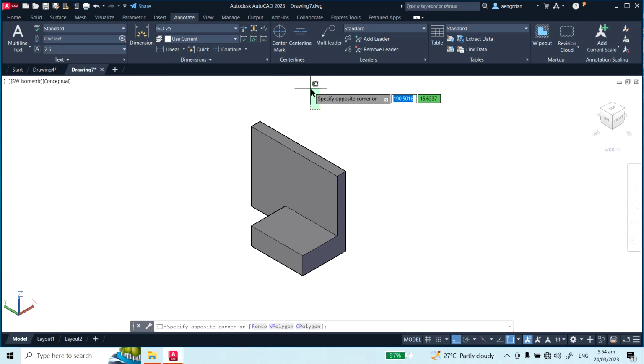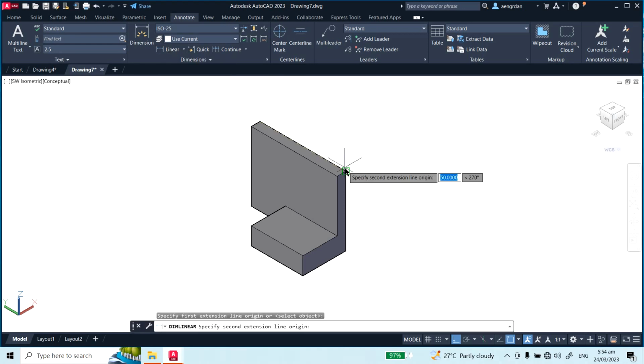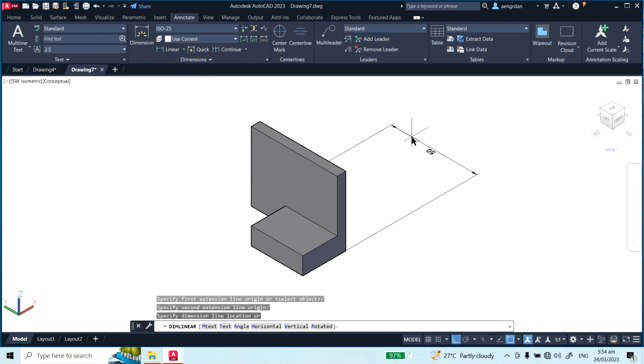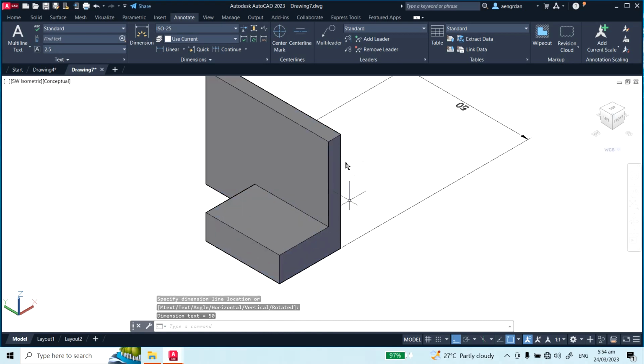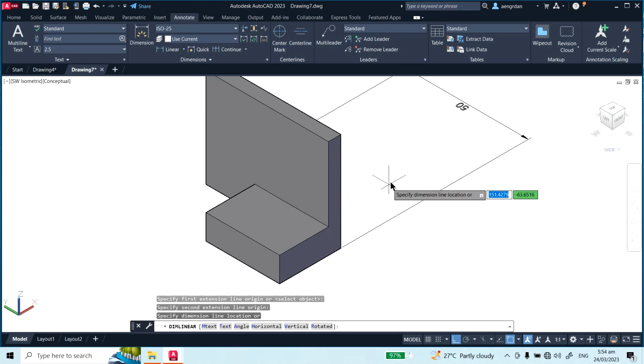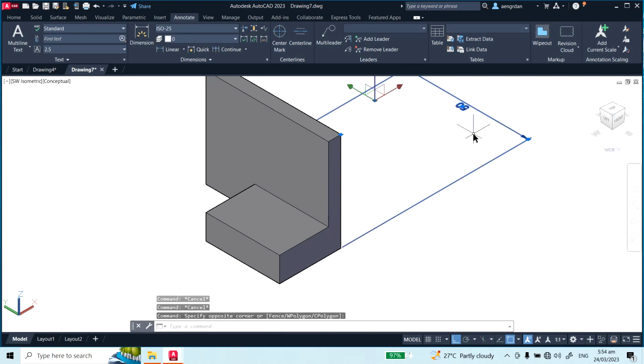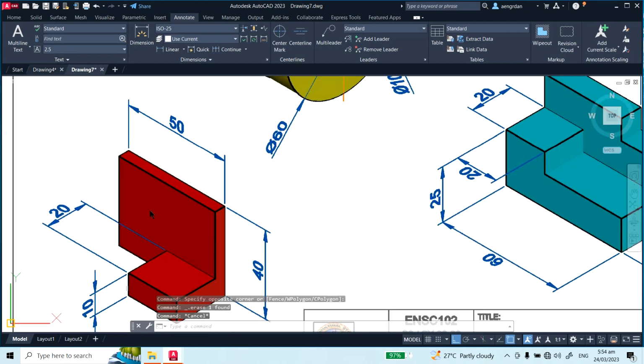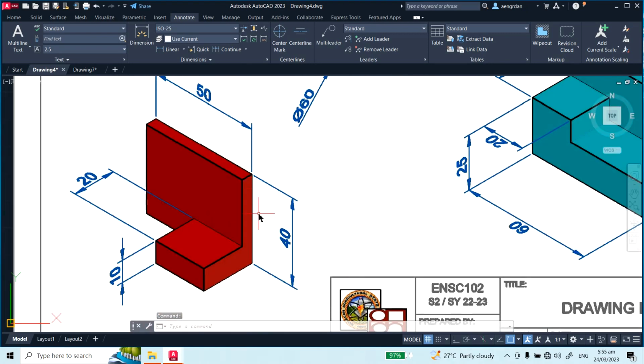In the 2D drawings, we just clicked the dimensioning tools right away and then specified the points. But this time we can't just do that. Let's say I want to put dimensions on this vertical length. We can't just do that because we need to change our UCS. Let's say I want to create these dimensions, 50 by 40. We can only execute these dimensioning tools along the XY plane. Therefore I have to change my UCS, making this face right here my XY plane.